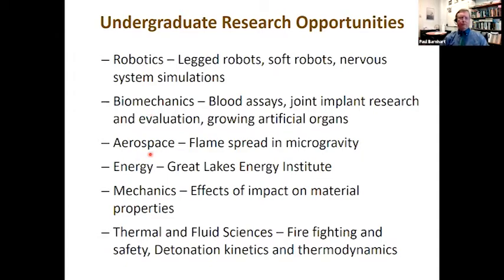There is some work being done in terms of what we call aerospace. A lot of this is being done in conjunction with NASA Glenn, which is a research center here in Cleveland, Ohio. It's about a 20-minute drive from campus. They have some great facilities our students work with. We're looking at flame spread, how flames spread across materials in microgravity. And in NASA Glenn, there's a drop tower. It's 500 feet deep. They draw a hard vacuum. They drop a payload so it can go through 5 seconds of microgravity before it impacts the bottom.